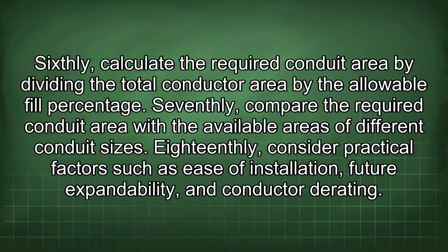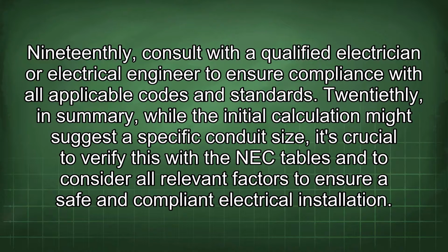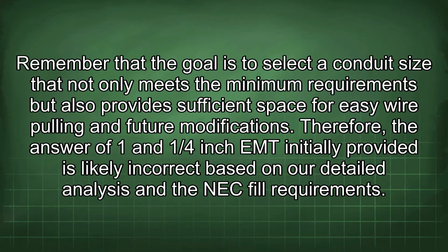18thly, consider practical factors such as ease of installation, future expandability, and conductor derating. 19thly, consult with a qualified electrician or electrical engineer to ensure compliance with all applicable codes and standards. 20thly, in summary, while the initial calculation might suggest a specific conduit size, it's crucial to verify this with the NEC tables and to consider all relevant factors to ensure a safe and compliant electrical installation. Remember that the goal is to select a conduit size that not only meets the minimum requirements but also provides sufficient space for easy wire pulling and future modifications.